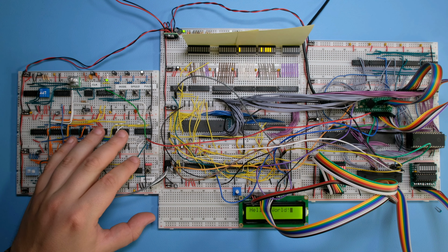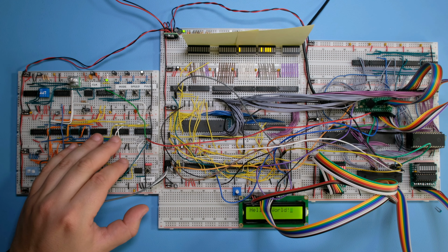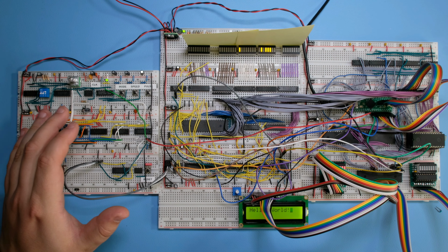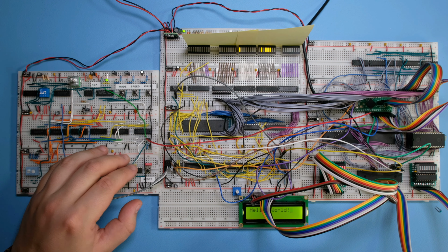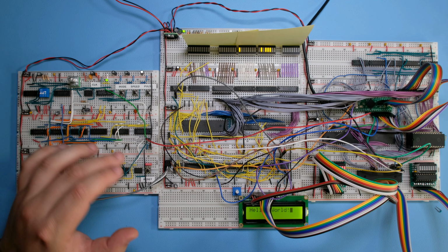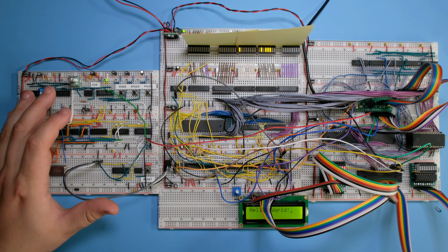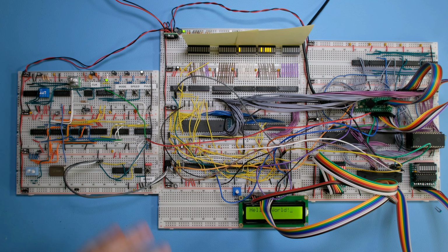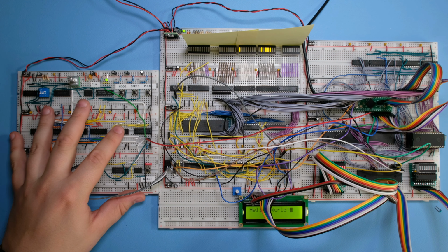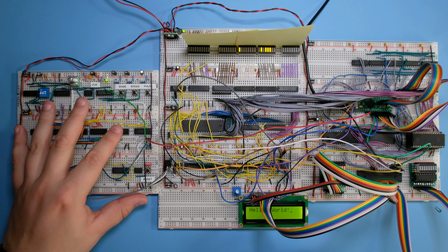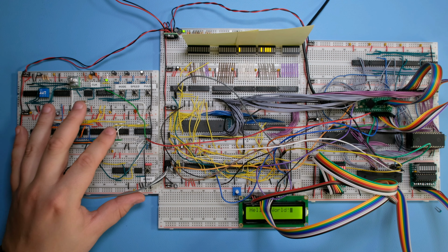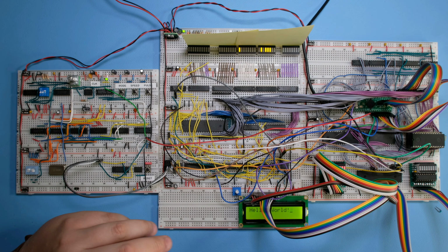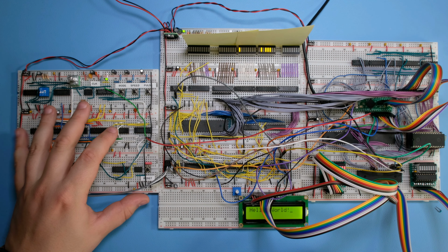We never computed before the maximum frequency that is safe for our switching circuits, and so we made sure to update our switching circuits and cap our maximum frequency based on those results. And so the maximum frequency that the clock can now run at is 5 megahertz, which is a bit of an overclock on the acceptable speed of the CPU, but I think that is fine. And we have the 3.33 megahertz frequency that is safe for the computer.